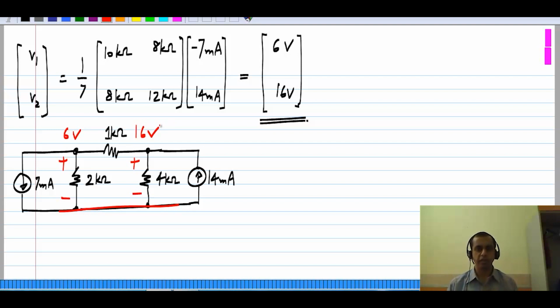Now it's quite common in circuits to point to one node and say the voltage at that node is something, let's say 6 volts. In those cases, it's understood that the other node is some implicit reference node, usually the reference node chosen for nodal analysis or what is indicated as ground in the circuit. Okay, a voltage is always measured between 2 points, so you have to be very clear about what the 2 points are when you specify a voltage.